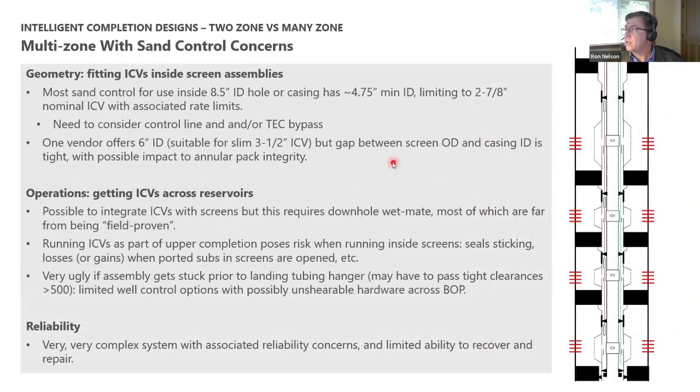And also, I have a slide here focusing on a multi-zone intelligent completion like this with 4 or more ICVs inside of a sand control completion. There are some additional concerns, and I did work on a design just like this for an operator in the U.S. Gulf some years ago. After we risk assessed it, we chose not to run it.